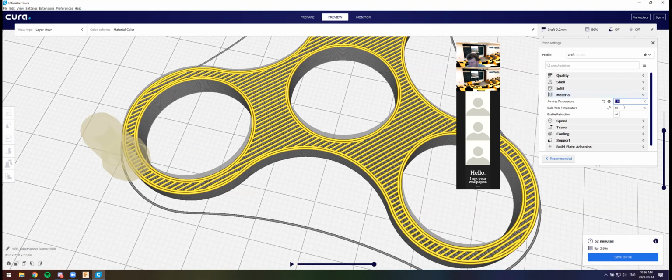But again, depending on your needs, you can edit this. And there are other filaments that melt at much higher temperatures. So for instance, there's another plastic called ABS, which is just a different type of plastic. It melts at like 240-ish, so you'd have to use a higher temperature for that. Yeah, so PLA is the more common one. If you're using PLA, 210 usually works really well.